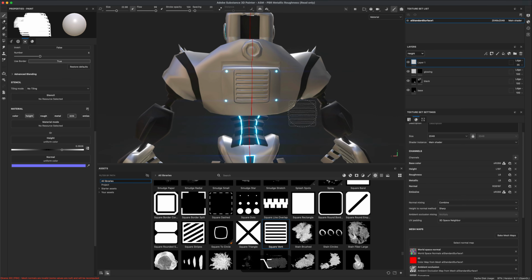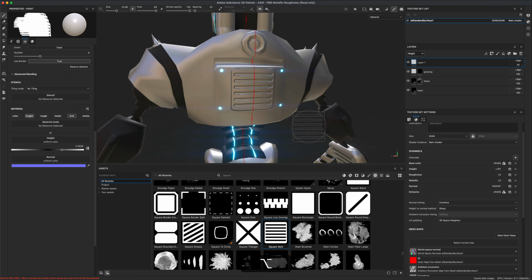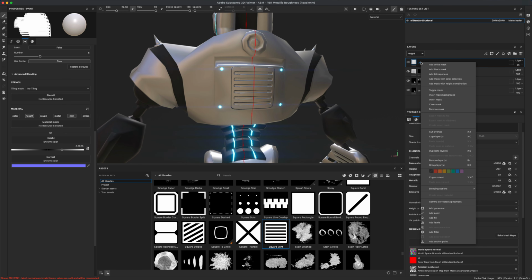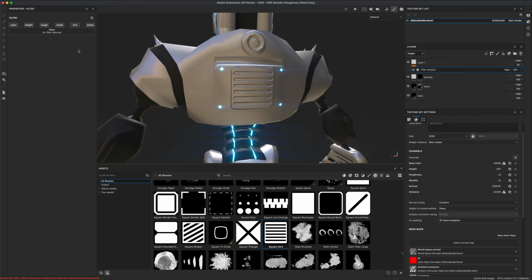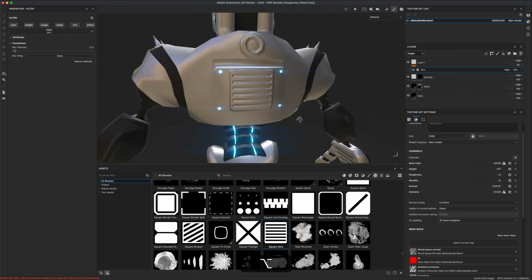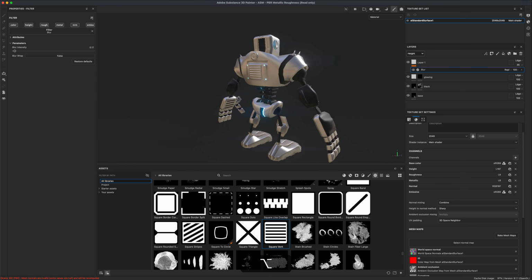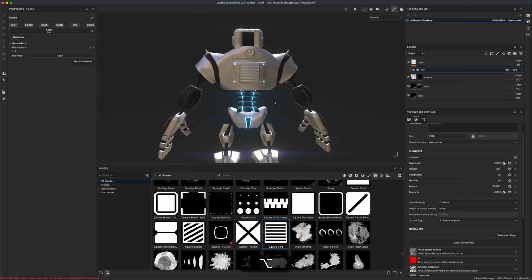For example, if I stamp something and I feel like it's a little bit low resolution, one of the tricks that I like to do is add a filter and do a little blur. You can control the blur, and you can see how, if your UVs are low res, it's a cool little trick to simply smooth it out, and it looks fine from a little further away.